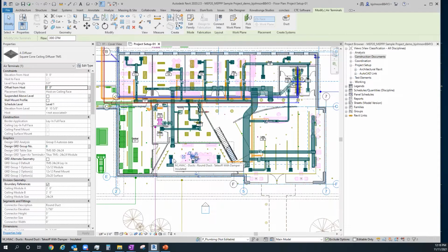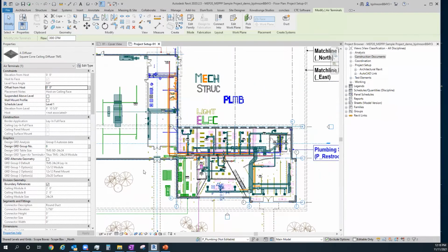Therefore, if we had things like CAD backgrounds instead of Revit backgrounds, maybe we're doing a renovation job or something like that, we could still load this all into Revit as CAD backgrounds for each level, and then go place individual objects instead of being face-based attached to a wall or something like that. If I only have line work, I can still place that along that line edge, and I have that symbol or that 3D object placed at true elevation. So have full coordination across all MEP.